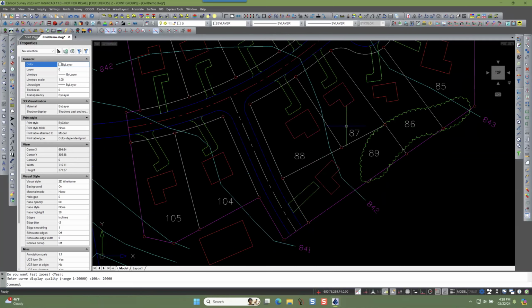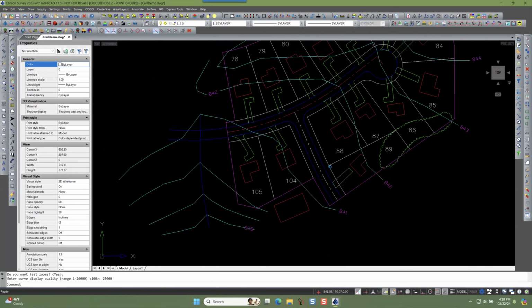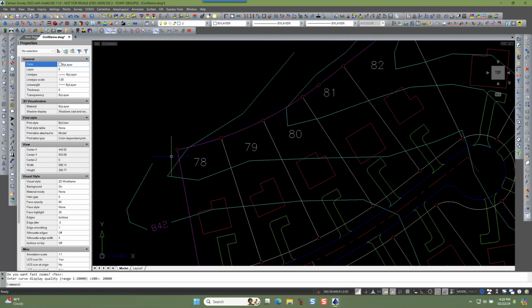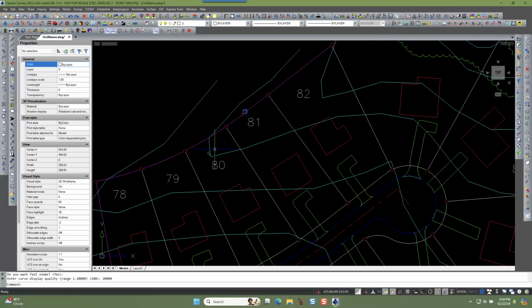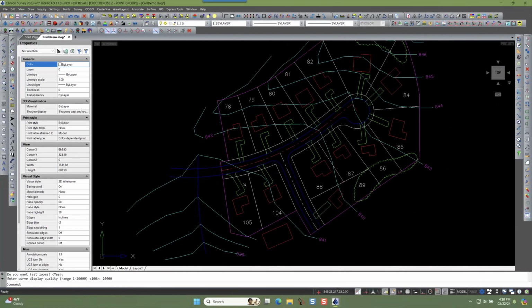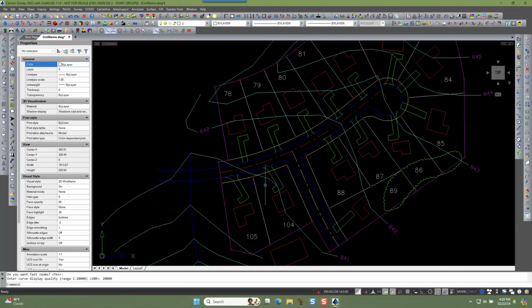So again, by using those point groups, I didn't have much to do here. I just used the group. I said, draw symbols wherever those point groups happen to fall, and that picks up all of these ones that I may have missed. And so that lets me add that to my property plat and show my corners as we go on.